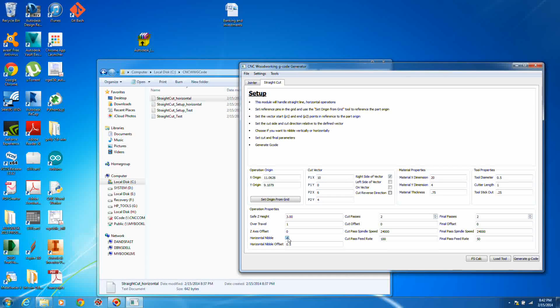And of course, in those cases, you would probably want to cut by nibbling vertically down into the piece. And again, you'd probably leave a 0.05 and then let the final passes clean it up so that you get a full depth clean pass. So yeah, it is a pretty powerful way of doing things at this point. It gives you a lot of freedom.